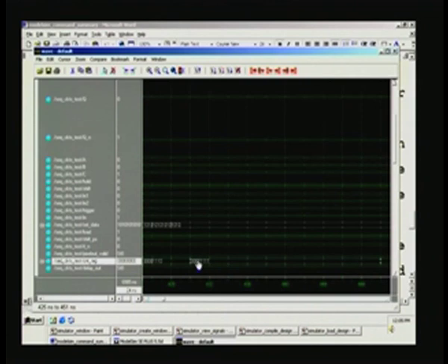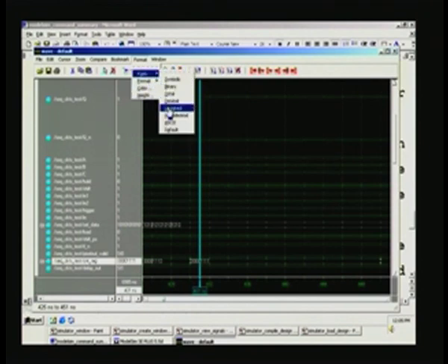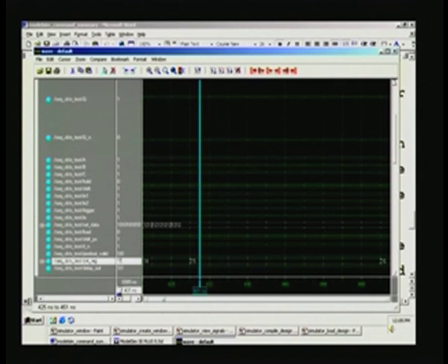This counter, let us say it is showing in binary. So, it is showing 4 ones. Let us set the format for that particular signal to, let us say, unsigned. Let us see what happens. It was 4 ones, so it corresponds to 15 in decimal, and if it is in hexadecimal, it is 0f. Like that, you can check various things.